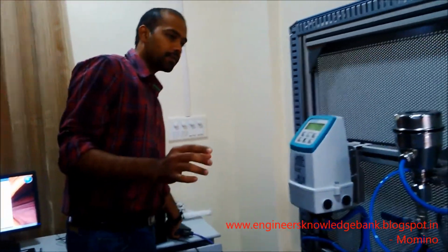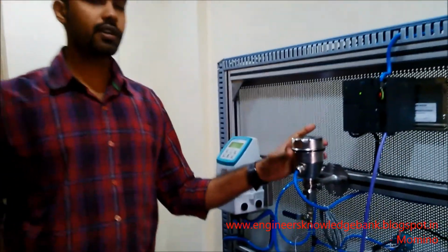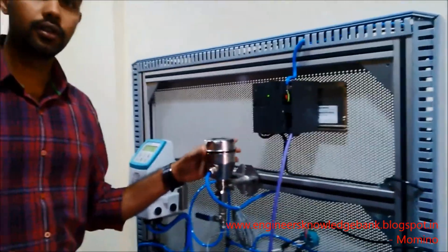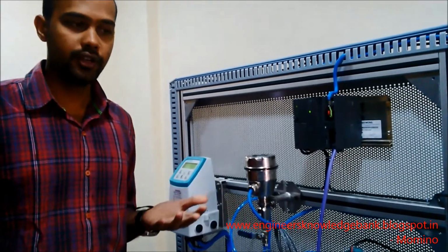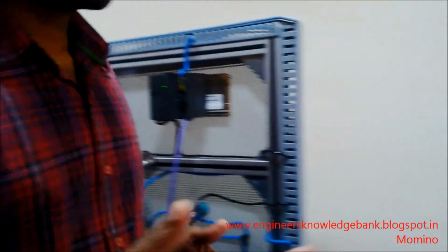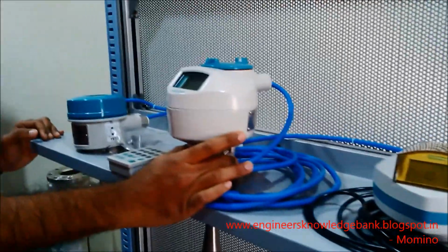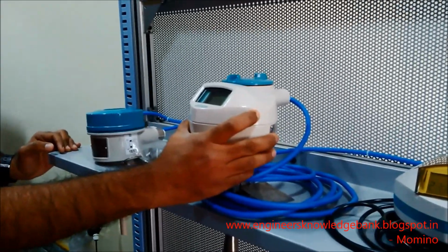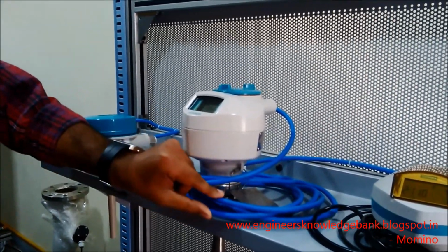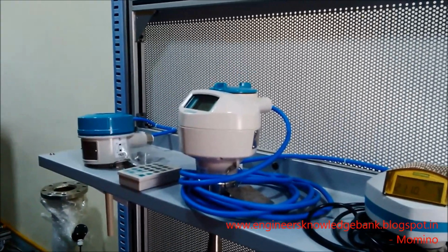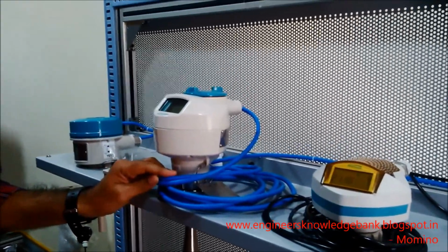This is the P300 pressure transmitter. It has a capacity of 1.3 bar, and we will see how we can communicate with it. On the other side, I will show you an LR250. This LR250 is a radar-type level measurement process instrument, and it is also connected to the PA cable. As you can see, it's connected to a blue cable, so it's connected to Profibus PA itself.